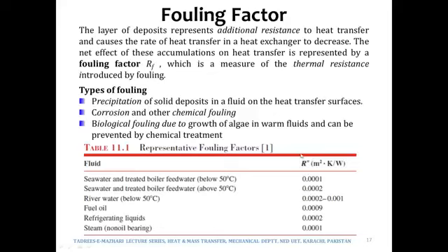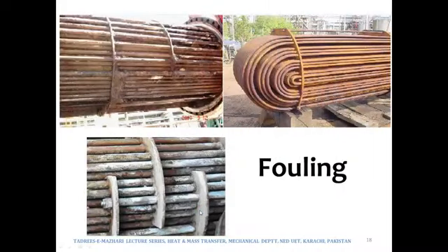Over here there are different fouling factors given per unit of area. If you take a look, R double dash means resistance per unit area, and we can also see from the units that the regular units of resistance are Kelvin per watt. However, if it is meter squared Kelvin per watt, that is resistance per unit area, which we discussed in chapter number 3, thermal resistances. So there are various fouling factors that can be taken. However, they will vary with the type of the fluid, of course. But nonetheless, that is a good point to start with.